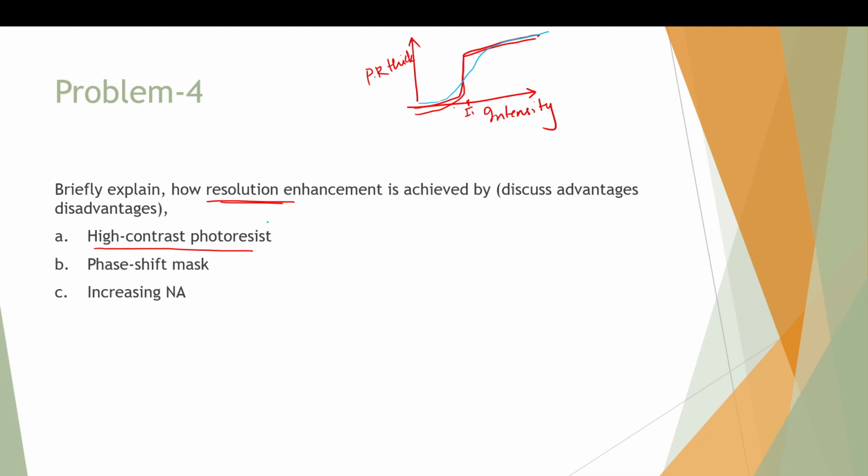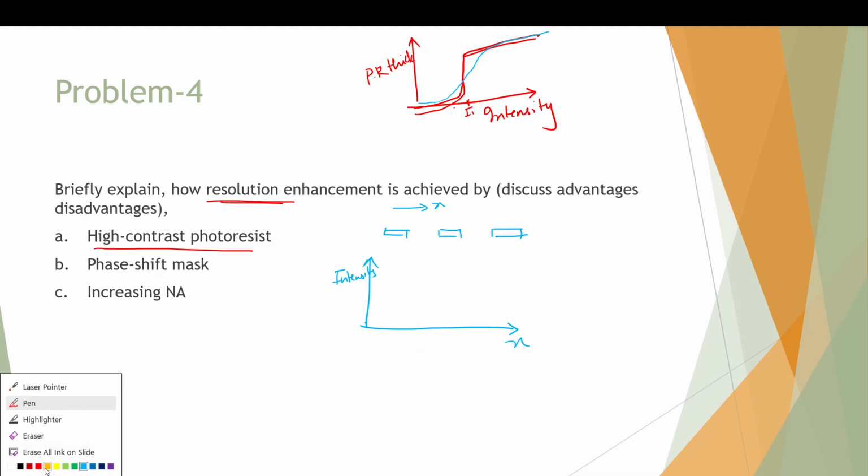Okay, so whenever we are exposing, the dose profile at the surface which gets exposed... say I have a mask like this, it opens in these two positions. When I plot the optical intensity versus the position, say this is the x axis, and this is the intensity of light that comes to the wafer. Ideally I will obviously want a profile like this.